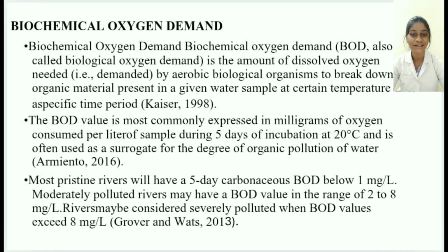It is also called biological oxygen demand, the amount of dissolved oxygen needed by aerobic biological organisms to break down organic material present in a given water sample at a certain temperature over a specific time period. The BOD value is most commonly expressed in milligrams of oxygen consumed per liter of sample during 5 days of incubation at 20 degrees Celsius and is often used as a surrogate for the degree of organic pollution of water.